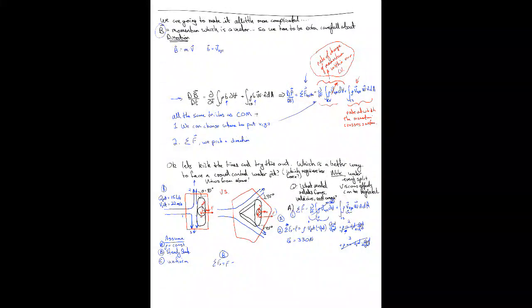And that's going to be equal to d/dt of the integral over our control volume of rho vx dV. Now, remember, again, this is equal to 0 because we are in steady state condition. We don't have any momentum accumulating in our control volume, right? So that's going to be equal to 0. Plus, our second integral now, again, we have to take into account each of our entrances and exits.